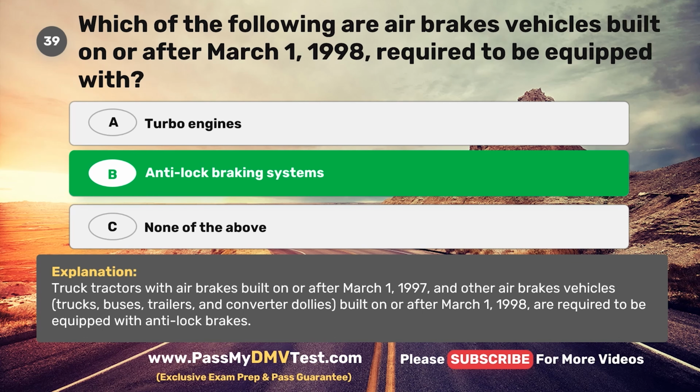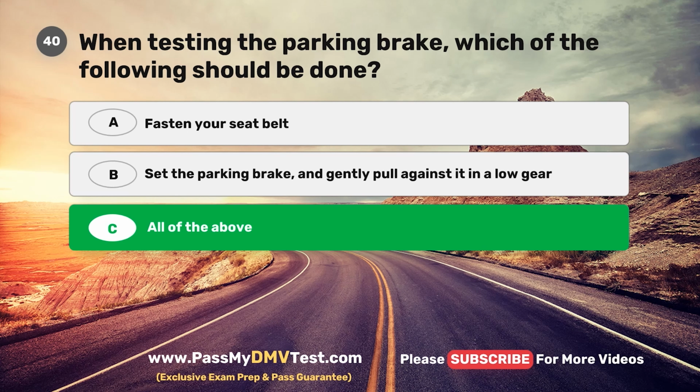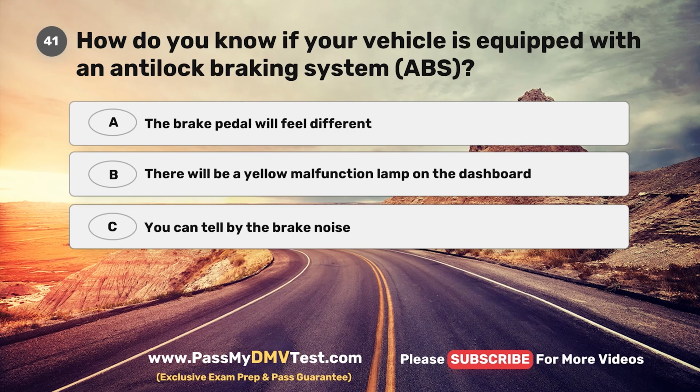Question 40. When testing the parking brake, which of the following should be done? A. Fasten your seat belt. B. Set the parking brake and gently pull against it in a low gear. C. All of the above. The correct answer is C. All of the above. To test the parking brake, first fasten your seat belt. Then set the parking brake and gently pull against it in a low gear to test that the parking brake will hold.